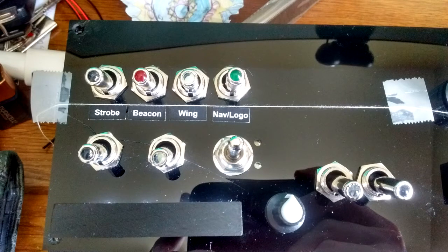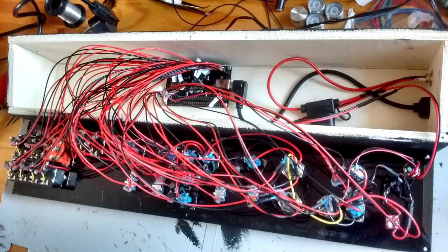Now it's time to put the labels and the knobs of the rotary encoders. I used the glue gun on the solderings of the DuPont cables to avoid them breaking. All the DuPont cables are connected to the LeoBodnar boards with the black wires on the outside. All that is left is to bind the buttons in the simulator.